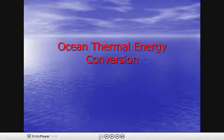We make use of a temperature difference. Between the surface temperature of the ocean and the depth of 1 kilometer up to 1.5 kilometer, a temperature difference of 14 to 15 degrees centigrade will occur. The atmospheric temperature lies between 25 to 30 degrees centigrade, and the sea level temperature is around 27 degrees centigrade.